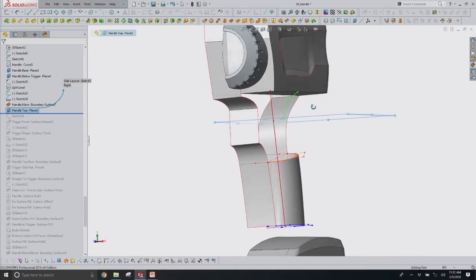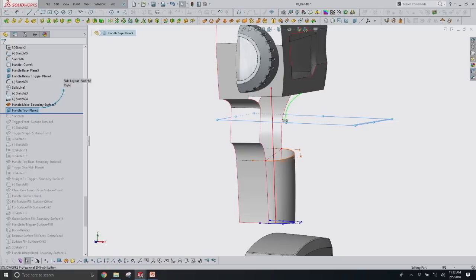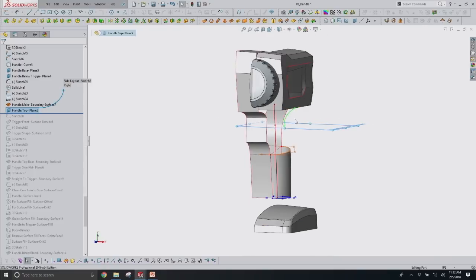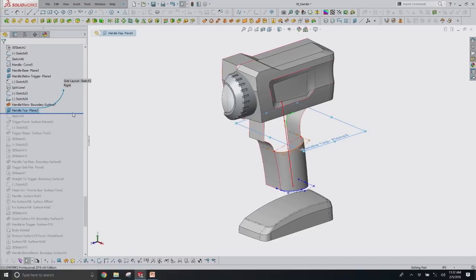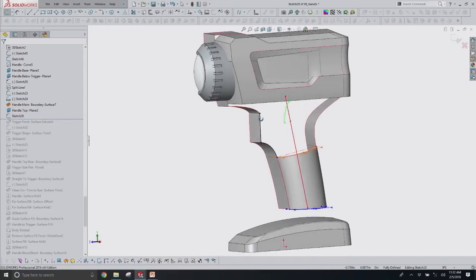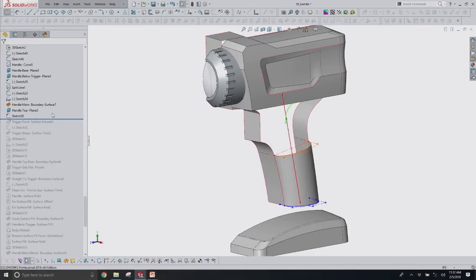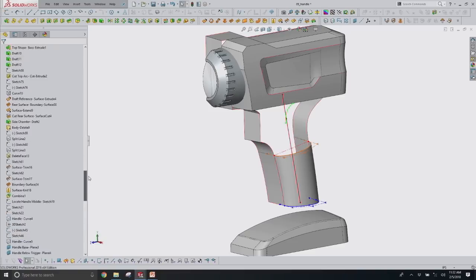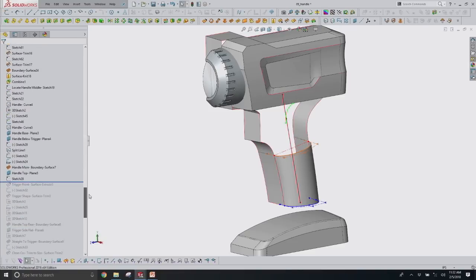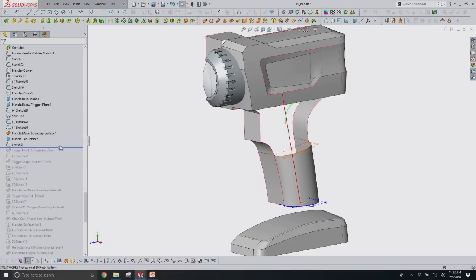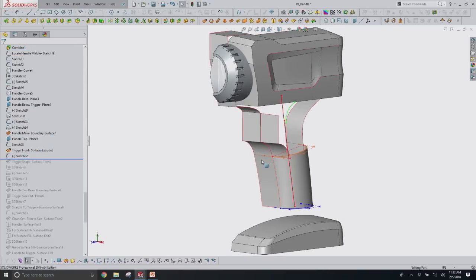So finally, I've got this one point here. We can see that I've got this sketch that transitions to this existing model edge. So I developed a sketch here. Oh, this is just a converted sketch. One thing I'm working with here, just so it's easier for me to find the sketches, is the flat tree view, so nothing's absorbed. Normally these things are all living in folders, but in the flat tree view, all of the sketches are here for me to easily show.